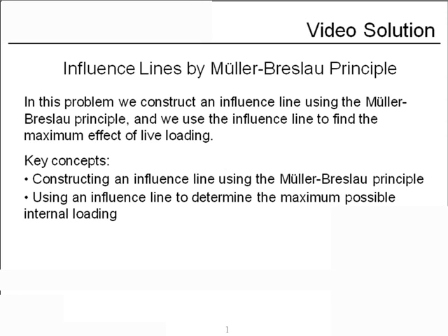A potentially faster way to construct influence lines for beams and frames is the Muller-Breslau principle. So that's what we'll demonstrate in this example. We'll not only construct the influence line using this principle, but we'll also use the influence line to find the maximum effect of a live loading. The key concepts we'll use are constructing an influence line using the Muller-Breslau principle and using an influence line to determine the maximum possible internal loading.